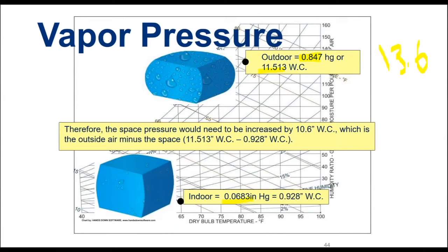So why do we pressurize the rooms? We pressurize the rooms so that the air volume itself, the cubic feet of air, does not come into the room and therefore bring in more moisture with so many cubic feet of air. We do not pressurize to try to stop or overcome vapor pressure. It just cannot be done.